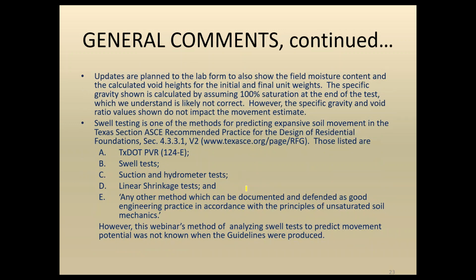Note as to that lab form, the one we'll eventually have available from this webinar, we intend to update it so that it shows the field moisture content and the calculated void heights for the initial and final unit weights. And then a comment again about that specific gravity calculation being based on assuming 100% saturation, which again is likely not correct. But for purposes of this presentation, the specific gravity and void ratio values don't impact the movement estimates we're discussing.